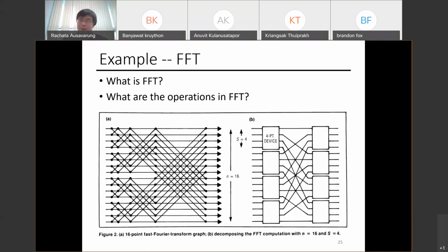So a lot of operations become cheaper. You don't have to integrate. If you have to integrate in the time domain, that is converted into a multiply in the frequency domain. So you can use the systolic array to do FFT.